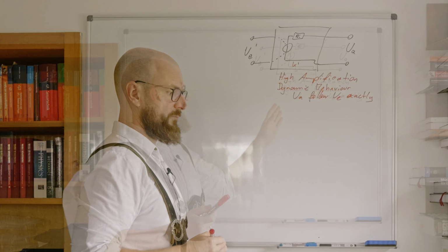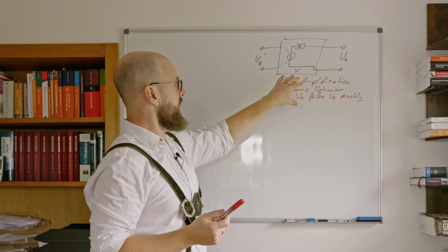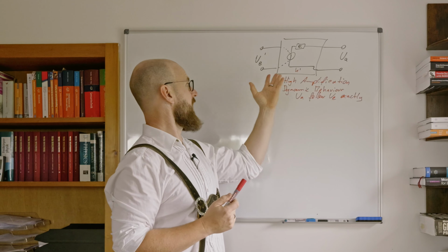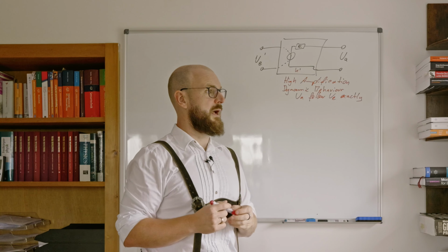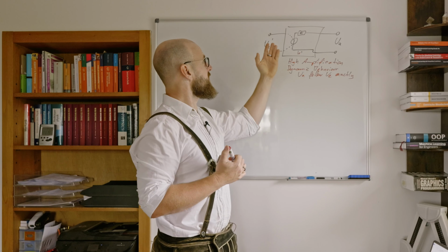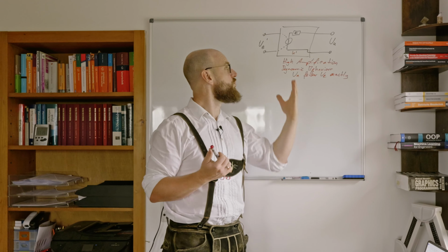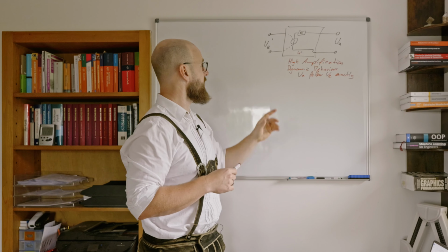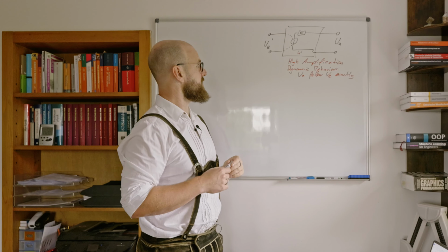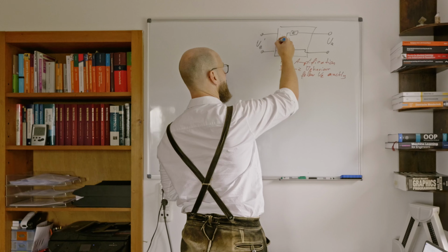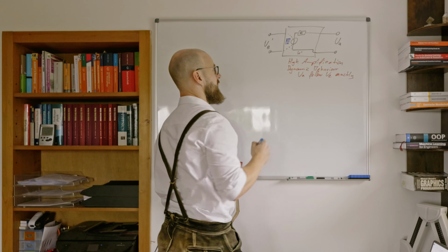That's important also. Having said so, there are some not so obvious things we want to have for such a measurement amplifier, which are that you should not need a lot of power to drive your measurement amplifier, meaning that input voltage should be connected to something with a very high resistance over here in the input.